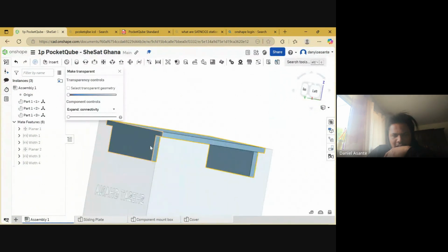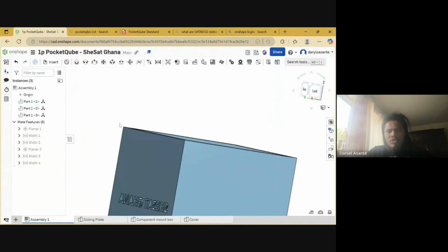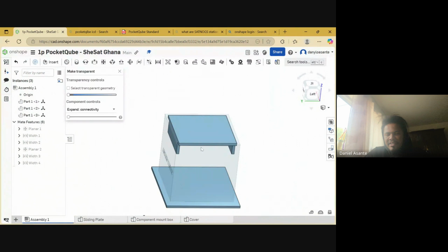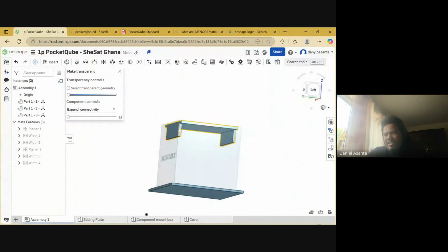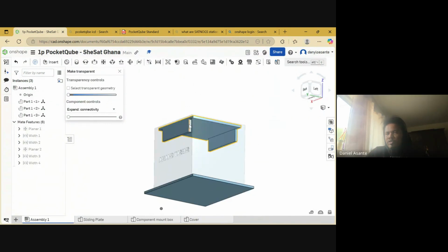So essentially why I made these extrusions here was because I would make a hole on the cube also. And then when I 3D print it, I'll put a screw there and just screw stuff to fix the top plates. But also remember all these things depend on what is inside your pocket cube. You can have PCBs or a camera here. So you need to know how much this would weigh, or maybe you need to change your way of mounting to ensure that nothing is interfering. But because it's a trial demo and there's nothing inside, I just assumed it to 10. But mostly this depends on what you're putting inside, to ensure that nothing interferes with anything.